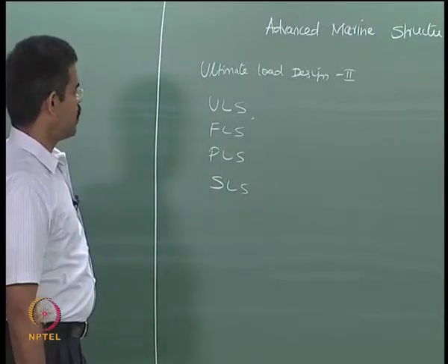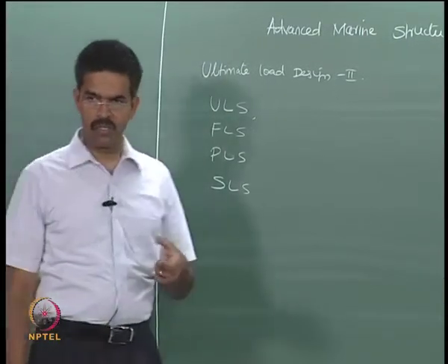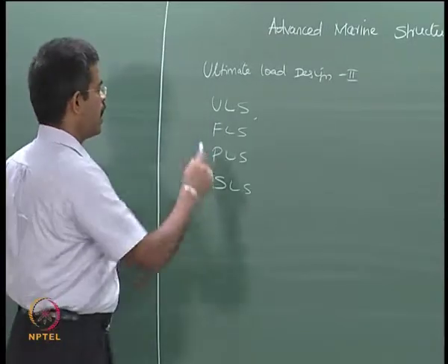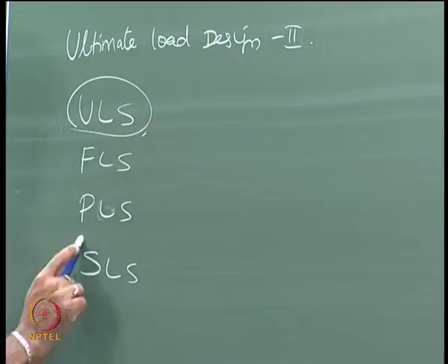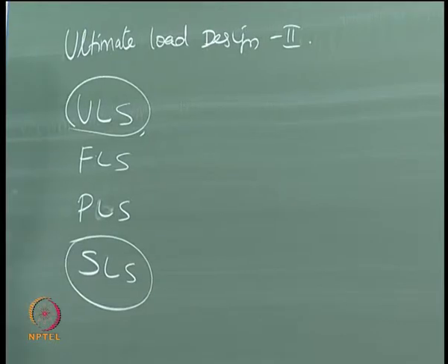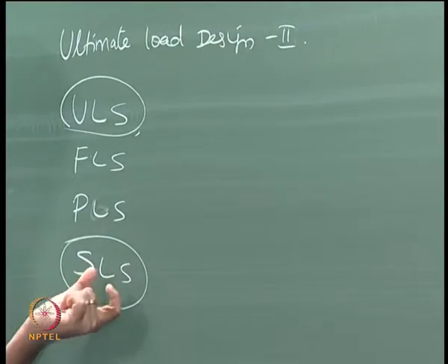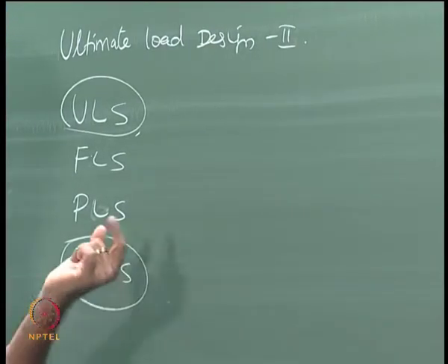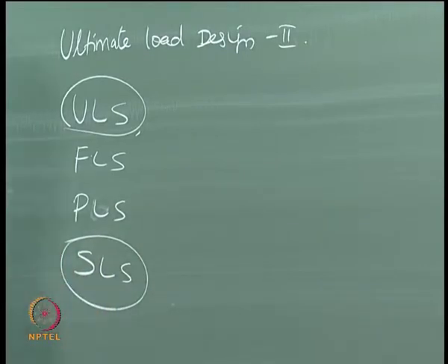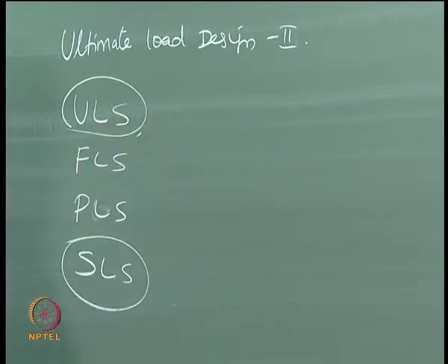We also understood the difference, and the critical questions which are binding the ultimate limit state and limit state of serviceability. Limit state of serviceability is a mandatory condition which must be met for every design principle, whereas ultimate limit state gives you an advantage of finding out the ultimate load carrying capacity of every member or a structure as a whole.